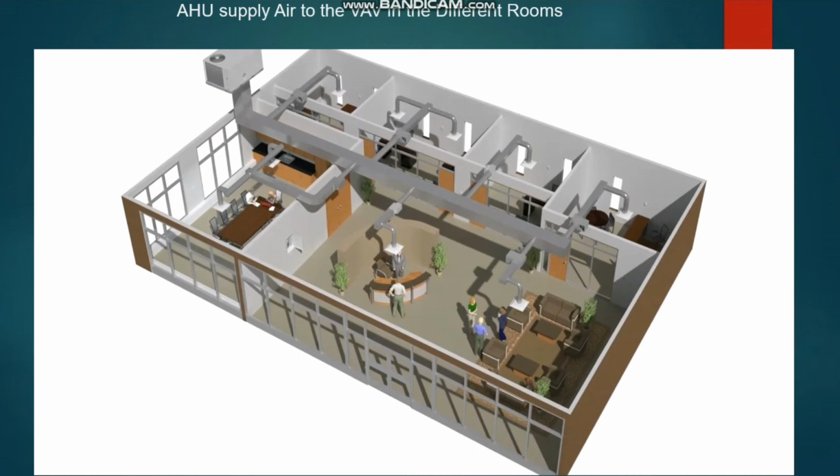So now coming to the next important question. For example, in this area, I need 5000 CFM. Okay, 5000 CFM I need. So can I provide only one VAV for this 5000 CFM or do I need to provide multiple VAVs? So how to select the VAV?